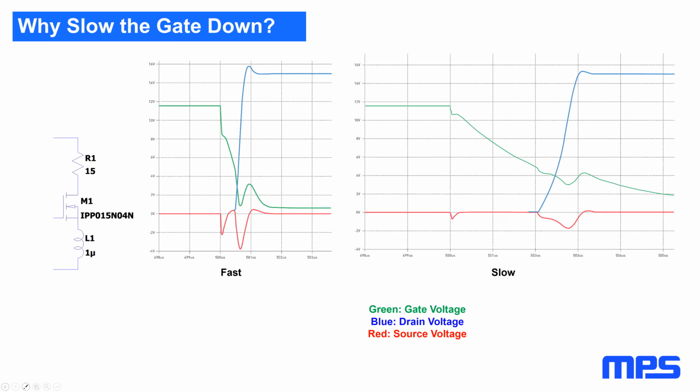So another parasitic effect to keep in mind is that the power supplies aren't perfect. They don't have 0 impedance. So when you drive a very fast transition into a load with some parasitic capacitance, and things like motors and solenoids have a lot of parasitic capacitance, then the current drawn instantaneously from the power supply is very large. We usually manage this by adding bulk capacitance to the supply. But the slower you switch, the less bulk capacitance you need to keep from inducing big glitches onto the power supply.